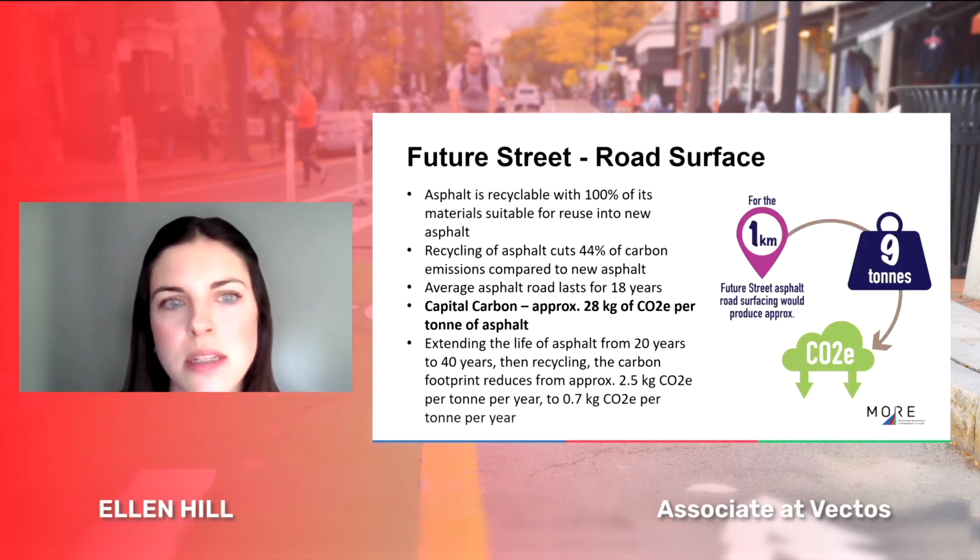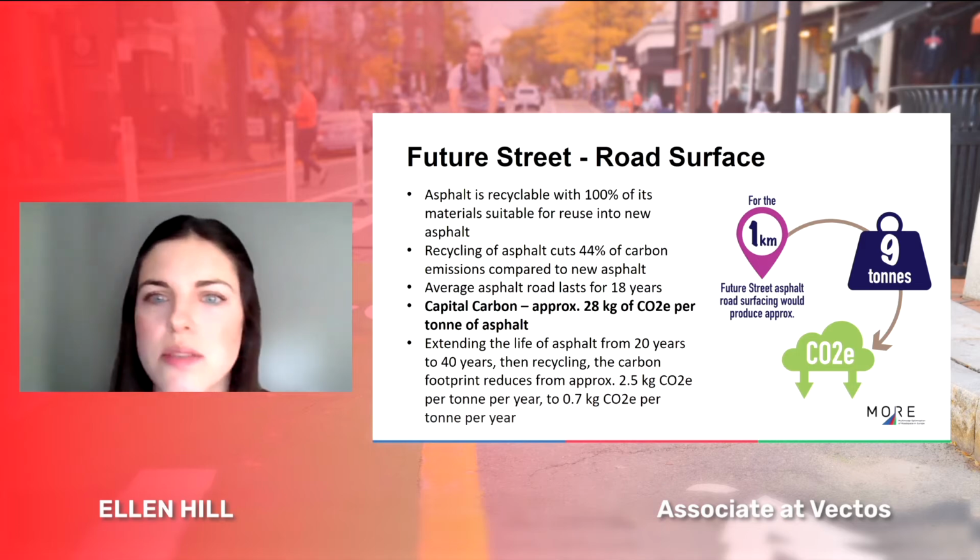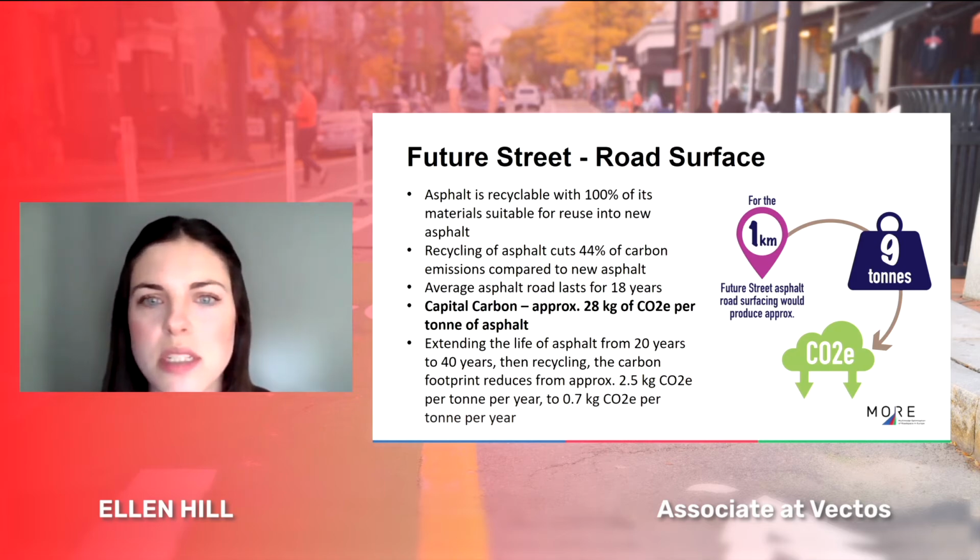Next slide, please. So looking again at asphalt for road surface, the material itself is fully recyclable, which can cut 44% of carbon emissions overlaying a new road using new materials. This means the embodied carbon value is around 28 kilograms of carbon dioxide equivalents per tonne of recycled asphalt. For the future street, this is approximately 9 tonnes of CO2e.